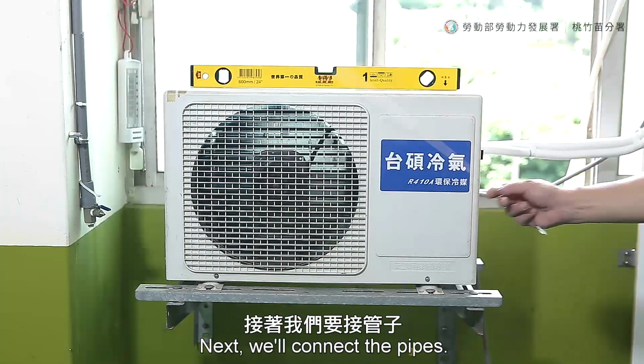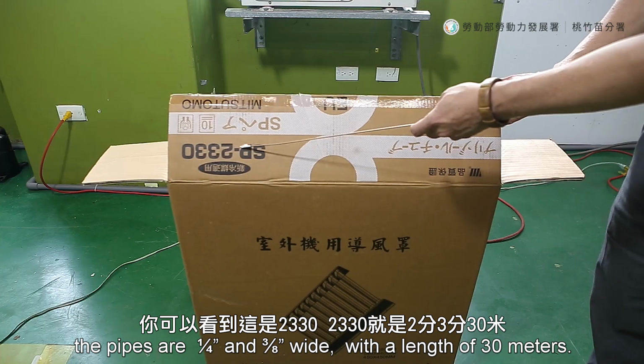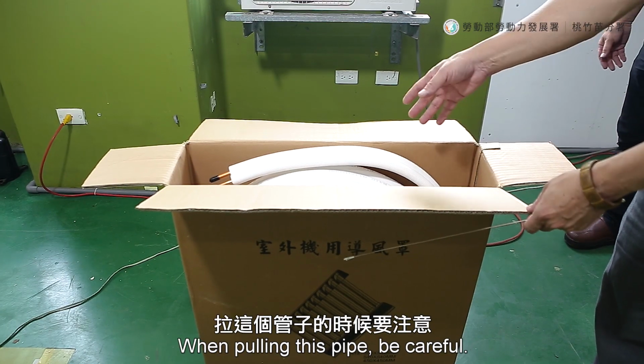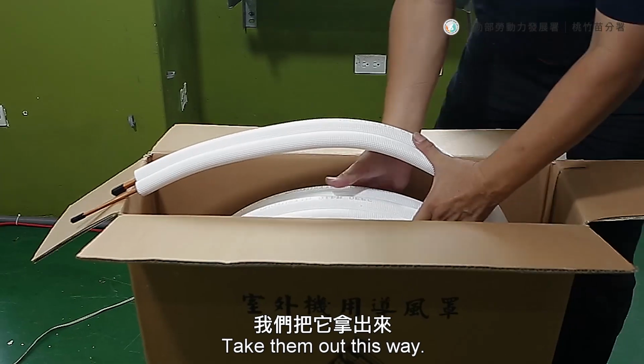Next, we'll connect the pipes. These are coated copper pipes. The pipes are 1/4 inches and 3/8 inches wide with a length of 30 meters. So the length of the pipes is 30 meters. When pulling these pipes, be careful. Don't pull the entire thing out like this. Take them out this way.